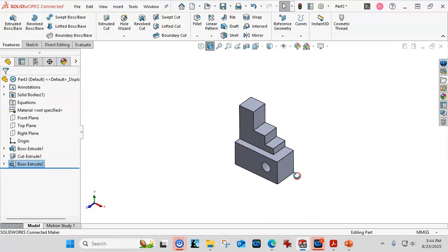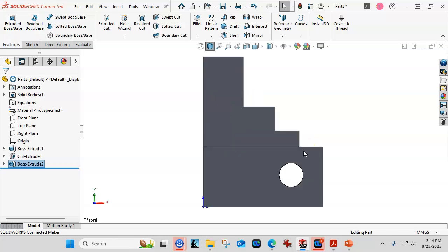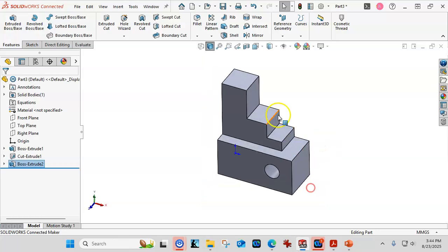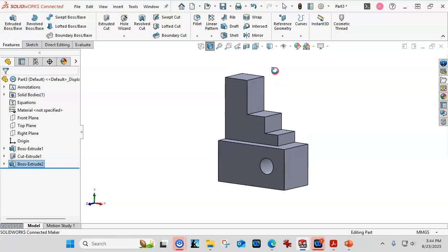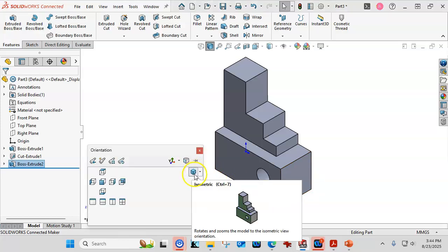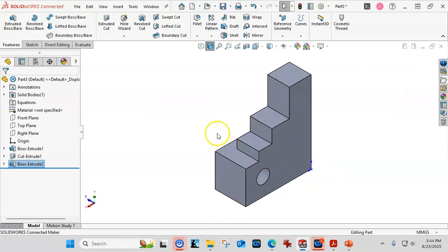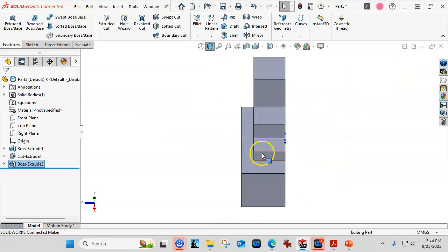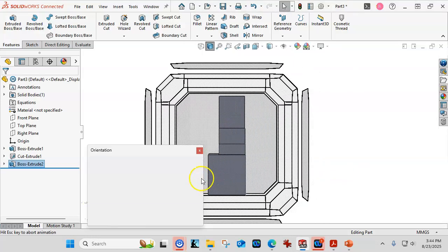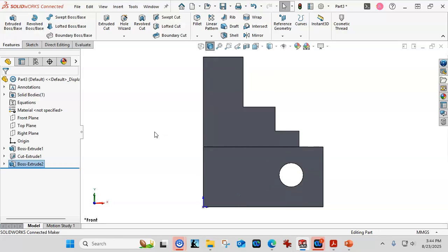You want to make sure that you have told it to extrude. And if you're looking at it straight on, it may not be apparent it's extruding the opposite way. So just be ready to rotate or go to Control 7. Oh, I said I was going to turn the cube on. If you like the cube, you can turn the cube on, and when you hit the space bar, you will get that thing and be able to rotate through the views. And I'm not as good at that as I am just hitting the control keys.